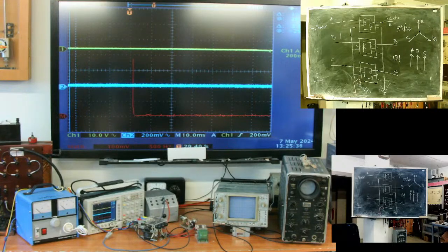Now influence is more visible. This is a tricky thing. At day, you have a loaded network and voltage at a lower permissible level. The change is because we are not in the saturation point, and the relative weight of the third harmonic is 7, 8, 9%, something not so heavy.